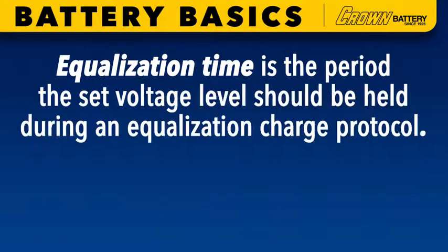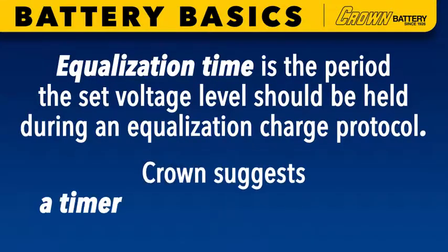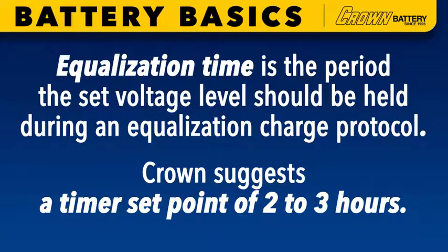Equalization time is the period the set voltage level should be held during an equalization charge protocol. Crown suggests a timer set point of 2 to 3 hours.